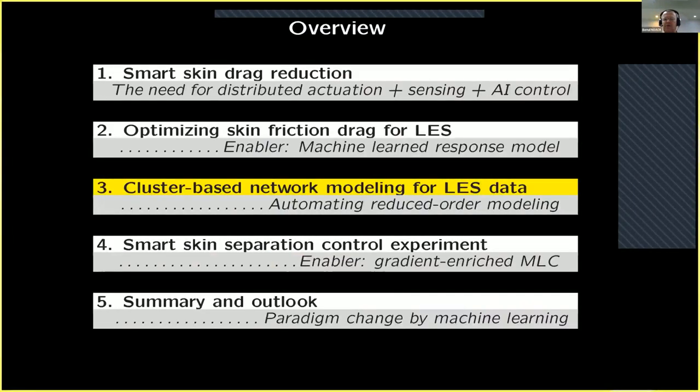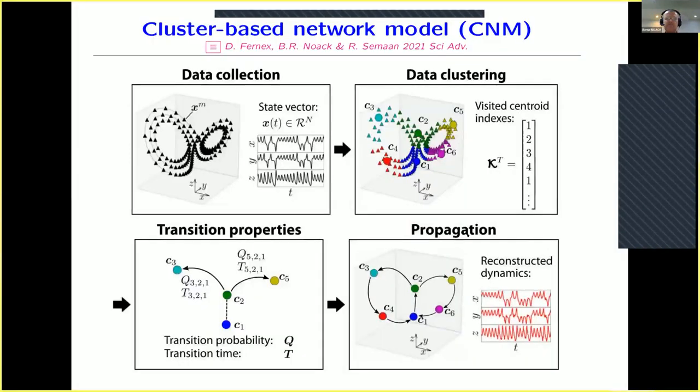Now we take a look at large eddy simulation data. Most of you will be aware of POD Galerkin modeling. This is pretty challenging for this broadband turbulence flow. So we use an alternative approach, which turns out to be much more robust, cluster-based network modeling.